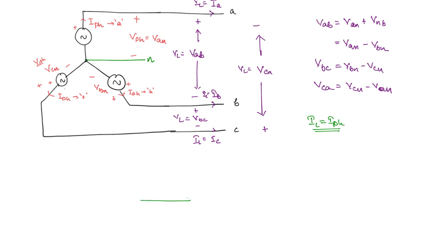So we will start with the phase voltages. Because we have the voltage sources here, we can take that the voltage sources are generating voltage with the required phase shift. Okay, so we can take this to be the reference values. So this is going to be VAN. What is this? It is a phase voltage. Then VBN, it will be generated 120 degrees lagging to VAN. Then what about VCN? This is going to be further lagging the VBN voltage. So these are the phase voltages.